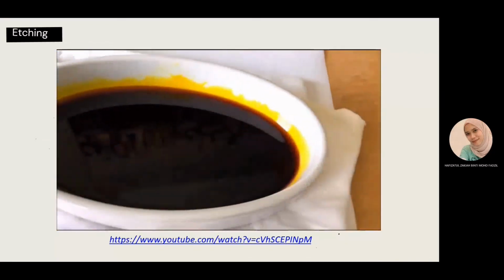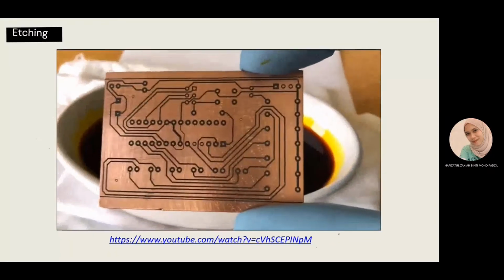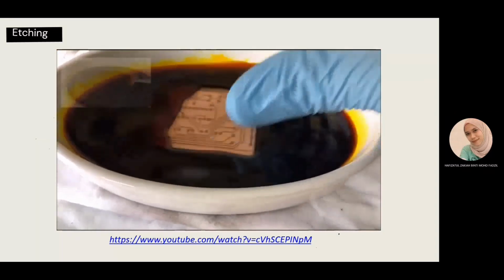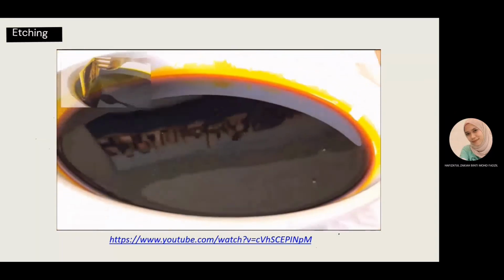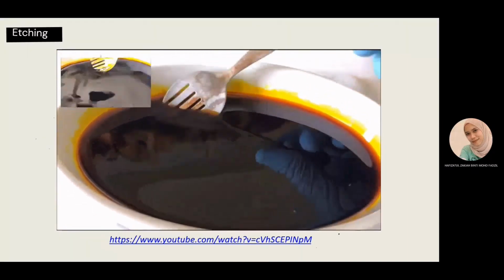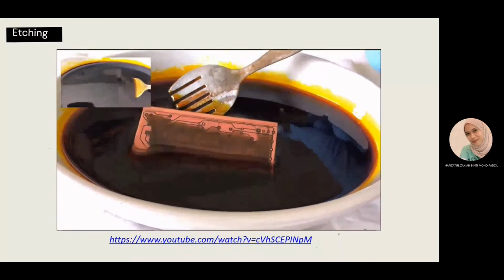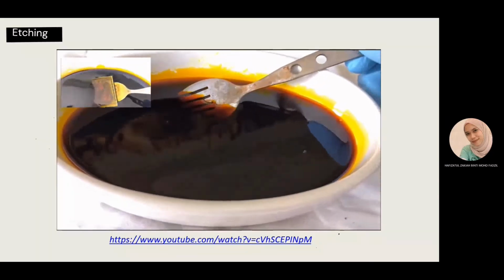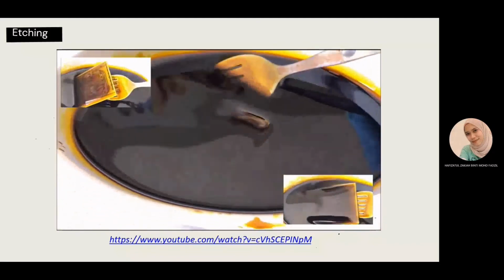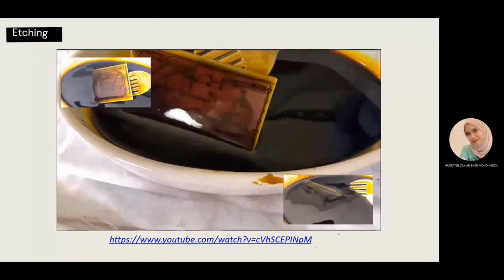Transferred off the magazine paper straight onto the copper board. Now when it starts drying you will get a bit of white tinge, and that's just a few fibres of the magazine paper. All I do is use a damp sponge, like so, ready for etching.